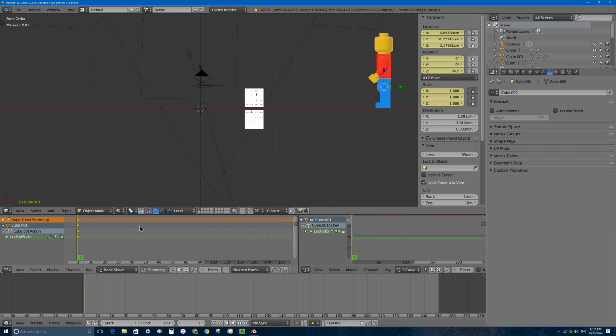That's what the Dopesheet editor window is for. It's good for blocking out your animation and for then going through the passes of your animation. In other words, going through again and again and making the animation better and better by refining your animation, looking at where things are and correcting things. So I want this animation of my character walking from here to take 72 frames. That's what I need for the length of my overall animation that I'm not really making here.